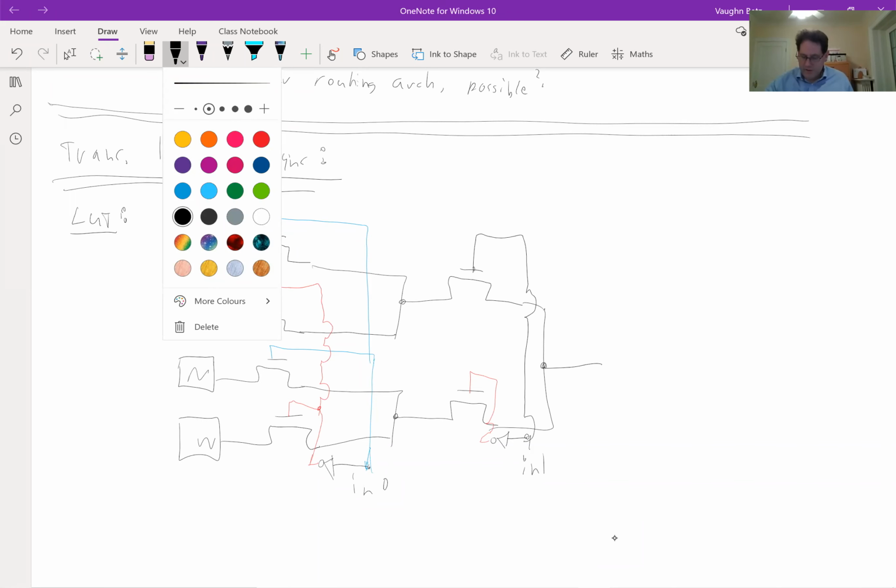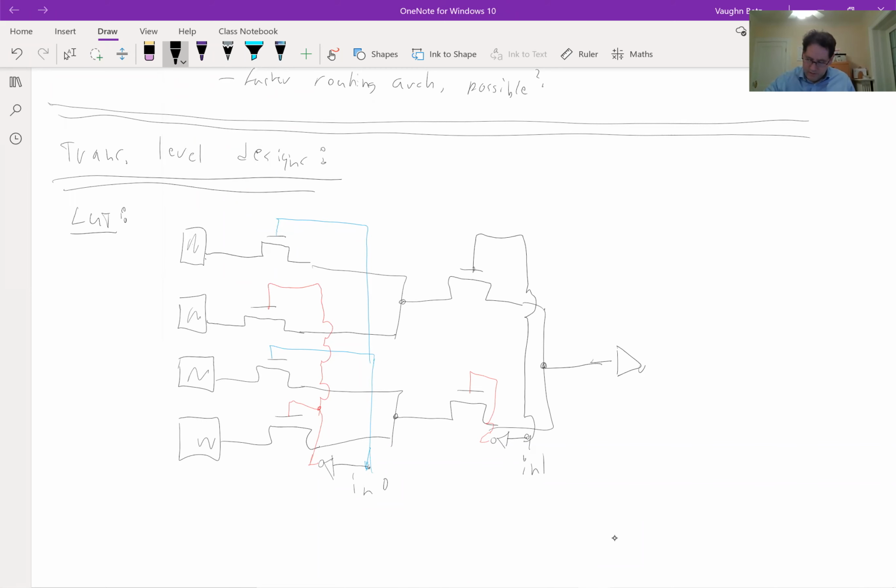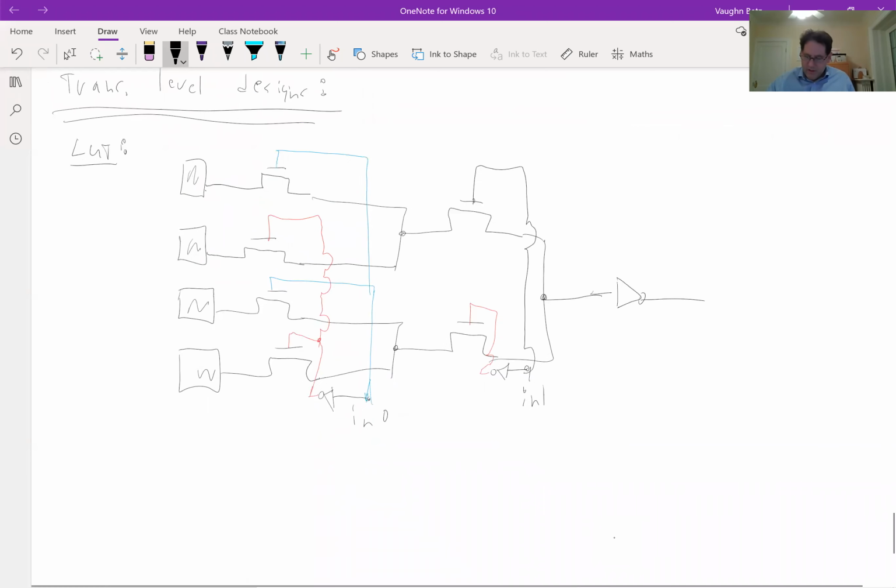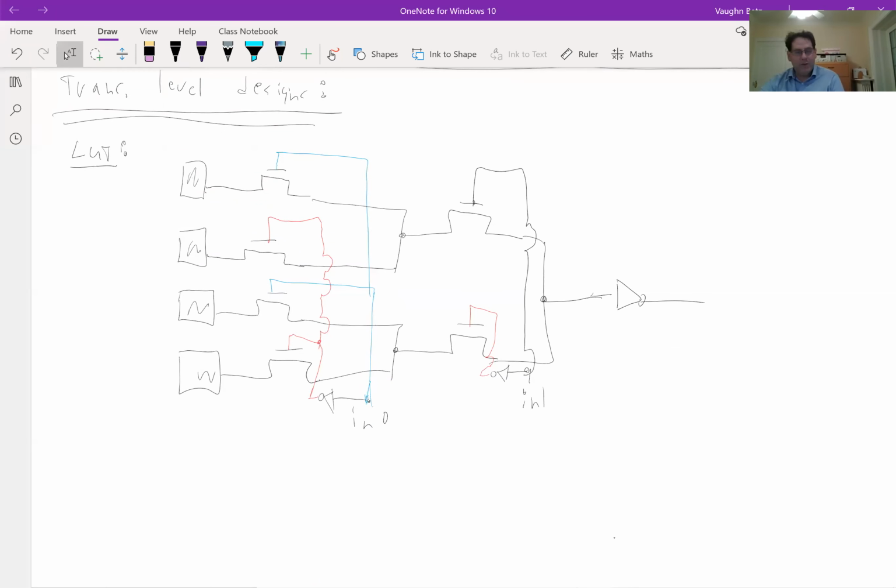Okay, so hopefully everybody can see that that is a 2-to-1 mux. This has poor drive strength. I've gone through from an SRAM cell. Let's say my input is 1, 1. Then if my input was 1, 1, my signal path is going to go like this, out to here. And I've gone through 2 pass transistors, which means that the output drive strength is not going to be very good. It's like I doubled the resistance of my pass transistor by doing that.